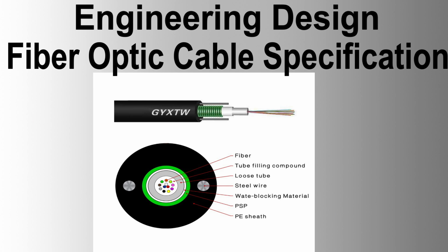Pressure tests. Blow through the conduit with compressed air to clear any debris. A lightweight mandrel dolly, foam, plastic, or rubber, similar to the one used for shooting in the FOC, shall be blown through the conduit to confirm it is free of water, debris, and obstructions. The pressure test shall confirm the conduit is airtight and waterproof, performed with at least 10 bar air, and no pressure drops allowed after temperature equalization for 30 minutes. The pressure drop shall be measured by a calibrated pressure recorder.